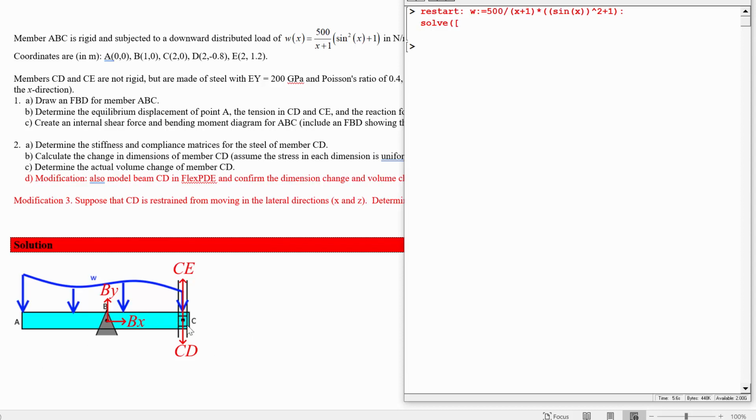The net force in x is 0, net force in y is 0, and net torque about any point we like is 0. And then we're going to have the other sets of equations, which will come from relating the geometry of this problem to figure out how the deformation of each of these beams is related, and the Hooke's law that relates their deformations to their forces.